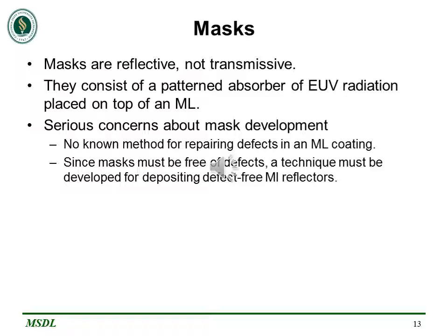Nonetheless, there are a number of serious concerns about mask development. The foremost is the fact that there is no known method for repairing defects in a multilayer coating. Since the masks must be free of defects, a technique must be developed for depositing defect-free multilayer reflectors.